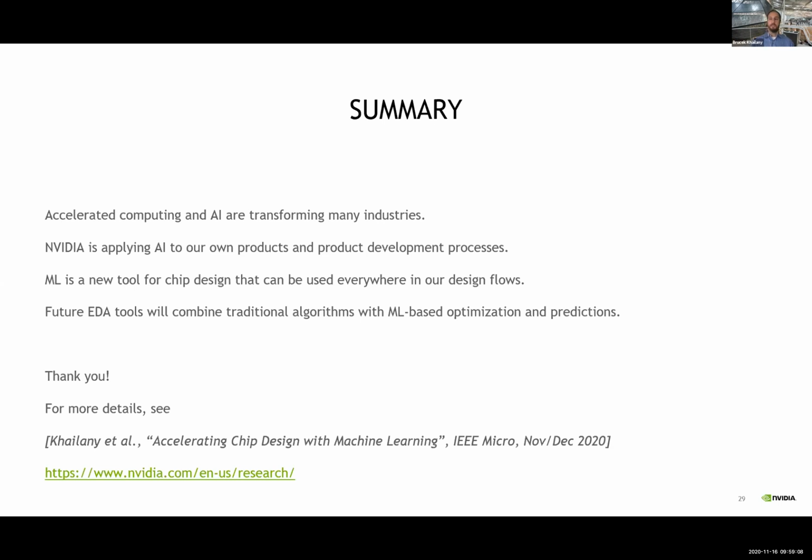In other words, you probably need to constrain things to something that's standard cell like, but it turns out when you go to FinFET, 7 nanometer and below, you kind of need to do that anyway, even for analog. In the old days of analog, you could do anything you want, right? But now you need to put things on grids. You need to have a standard power strap between VDD and ground, and say, okay, I'm going to put my rows of NMOSs here, my rows of PMOSs here. That highly constrains the design space enough that it seems tractable for DRL type solutions to work.